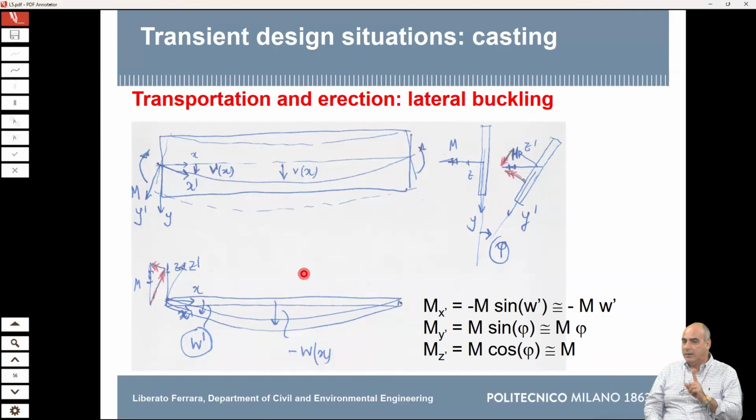The other important assumption, and this we always keep, because otherwise we will not be able to use our elements. When you design a slab, you check that the deflection is less than 1/200 of the span. Otherwise, I joke, if I throw an apple here, the apple will go to the middle of the room. But before this, your tile will jump up, your walls will crack, and so on.